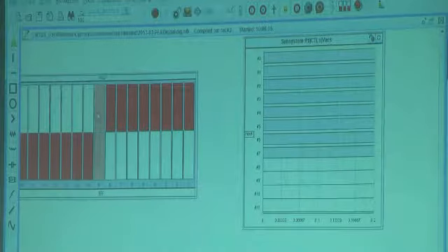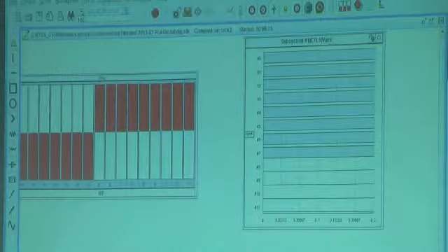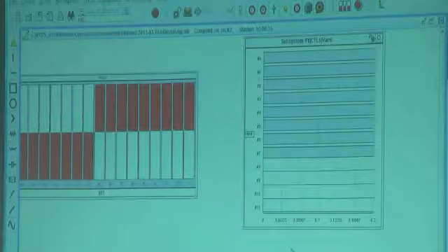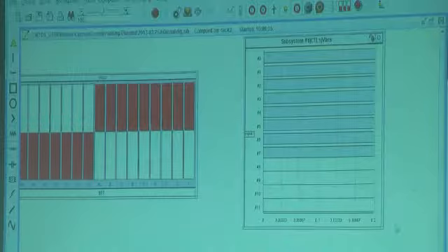But when I change number 9, it doesn't change. The cable has how many channels connected? Only 8. So channel 9 is not connected, so I won't see the change. Even though channel 9 on the GTDO card will be 5 volts, it's not connected to the GTDI. So I can't see it in runtime.